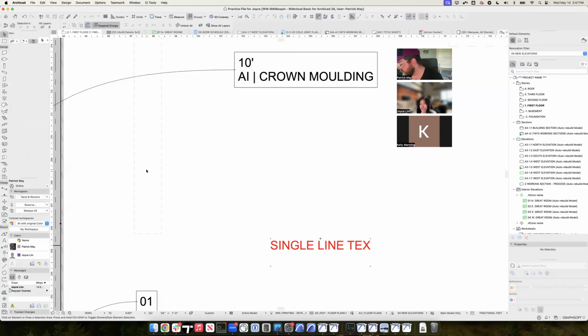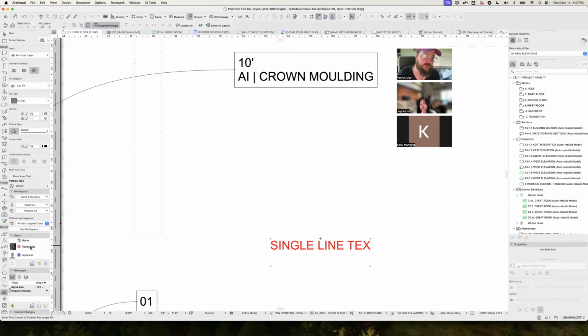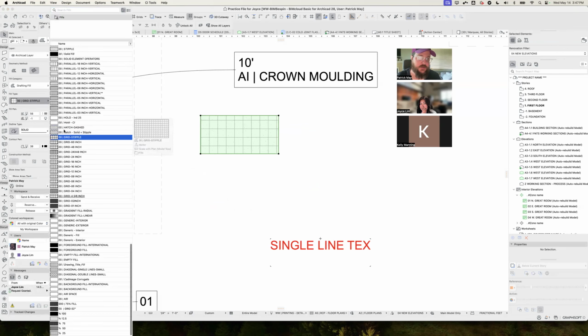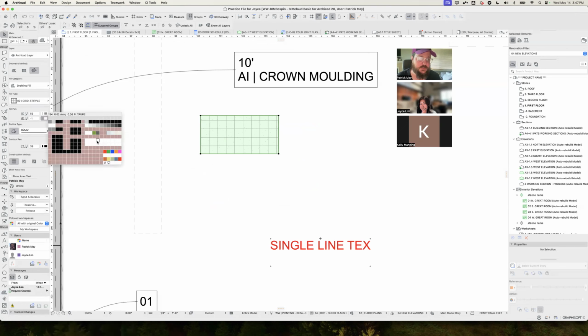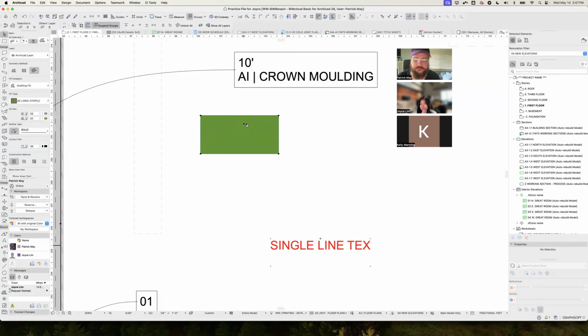And then the fill tool, it's even simpler. We talked about fills as attributes earlier. We do have the fill categories, but generally speaking, if I'm drafting fills, I'm going to use the drafting fill here. So real simple, it's just the pattern, whatever pattern you have with the foreground pen and the background pen.